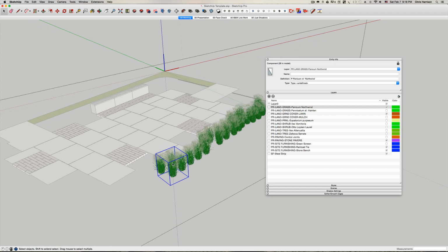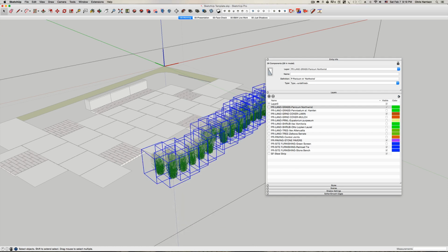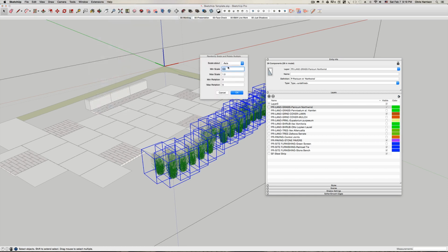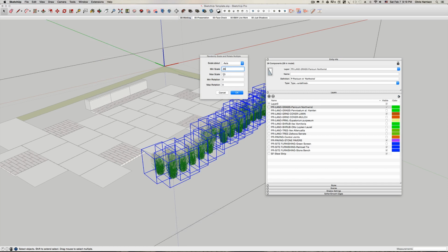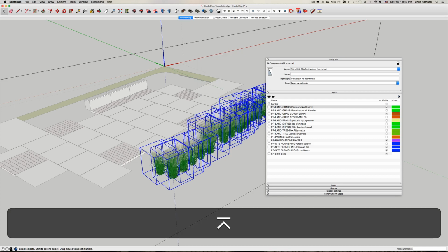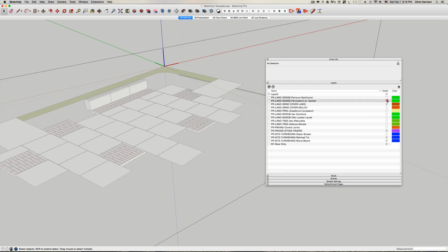So I am going to right click and say instances and say select all. You have this capability with your extension that you have to install, selection toys. And then I'll do another extension. It's Chris Fulmer, and this is scale and rotate multiple. And we'll do randomly, and we're just going to vary the size of these. So I'm going to say maybe it doesn't get too much smaller, but maybe it gets a little bit bigger, just to vary the size of those, and I will turn those off.